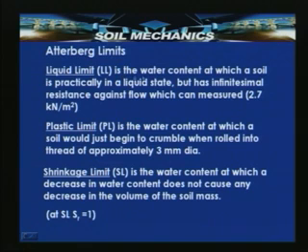So, as we defined, let us look into the definitions of Atterberg limits. Liquid limit is the water content at which a soil is practically in a liquid state, but it has infinitesimal resistance against the flow which can be measured. So, at liquid limit the soil has practically a small shear strength which can be measured. Most of the soils have a shear strength at liquid limit of around 2.7 kilonewton per meter square.